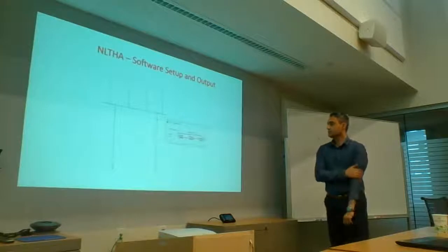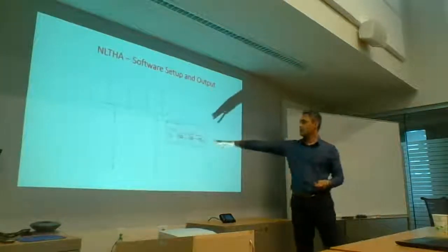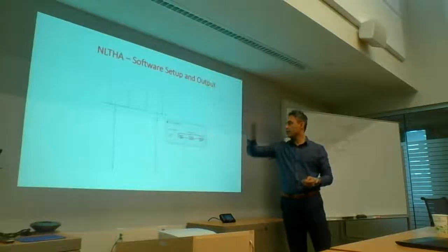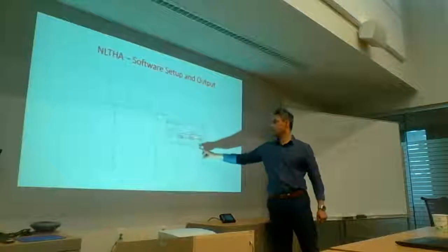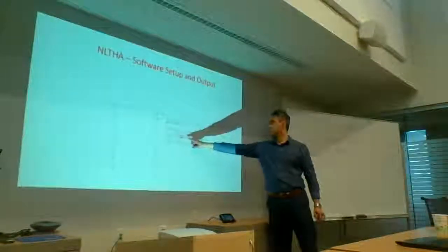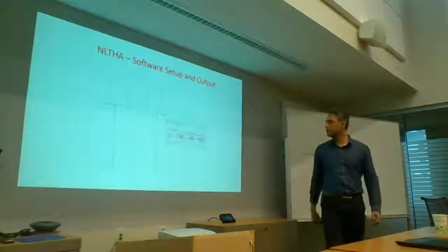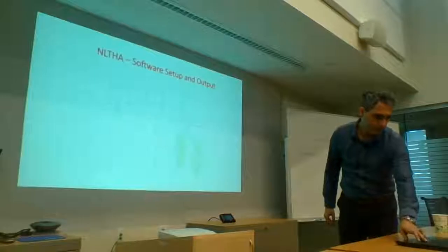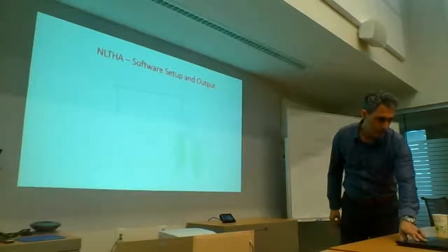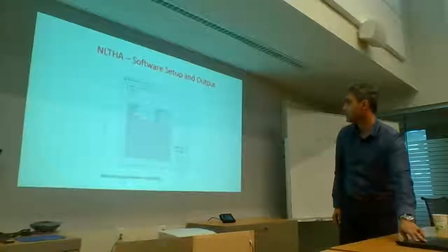Joint displacements, I can also ask for a maximum value, and it tells me that my joint 37 has moved 134 mils longitudinally, transversely it's 100, vertically it's about 25. And then it also gives me the rotations. This was part of a bridge we looked at.